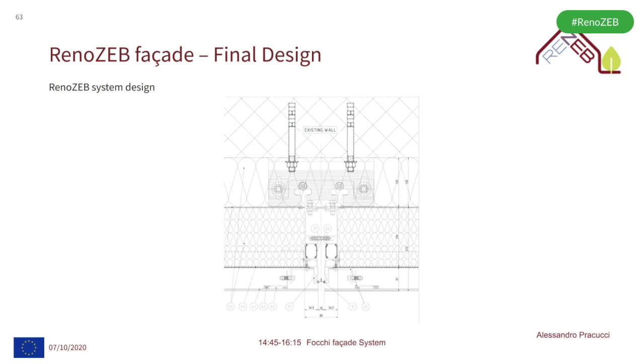In the case it's not necessary to fill this cavity with insulation, because the overall thermal transmittance of the new building envelope is enough for the norms or for the performance to be achieved, I can consider a fire stop barrier at each front slab, positioning specific mineral wool. In this case, it's quite common to use mineral wool. We can stop fire propagation and have a compartmentation for the cavity itself.